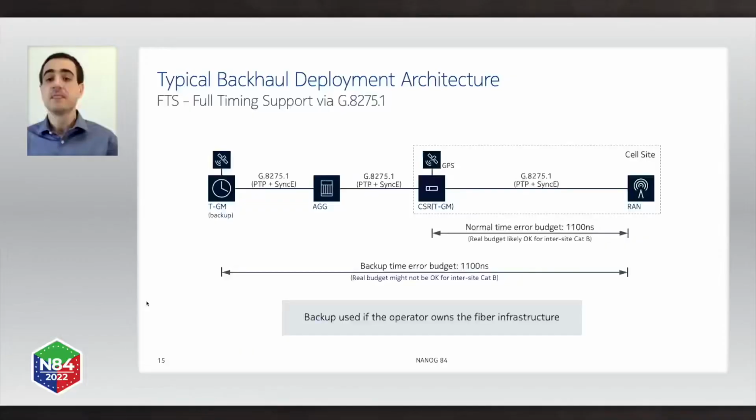It could maybe be jammed. There are ways to try to prevent that a little bit, but it could be jammed. Or if you don't have a good antenna positioning for the GPS, and that typically happens in urban canyons, think New York City, for instance, or anytime you were driving in a street with very high buildings in downtown, you probably lost GPS in your car, and the same thing happens with the GPS for the router. So if you don't have good visibility of the satellites, you might lose GPS from time to time. So if you lose that, you need a backup.